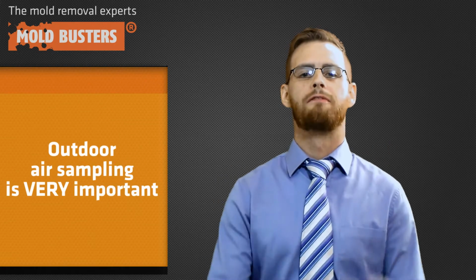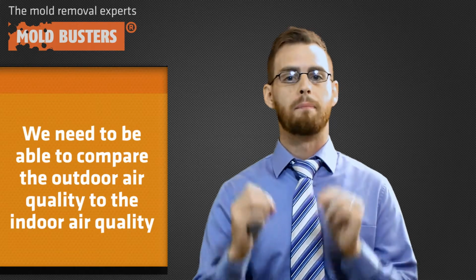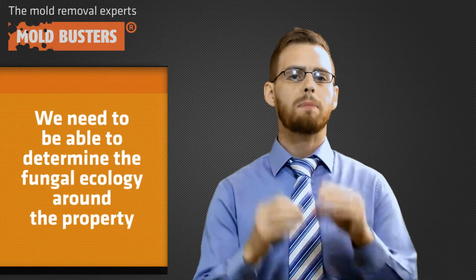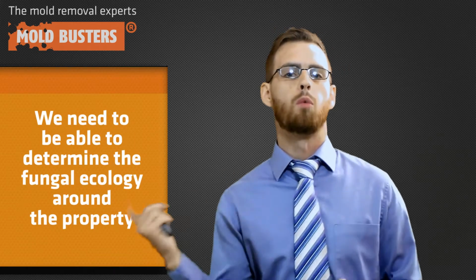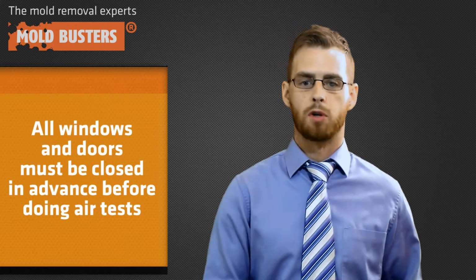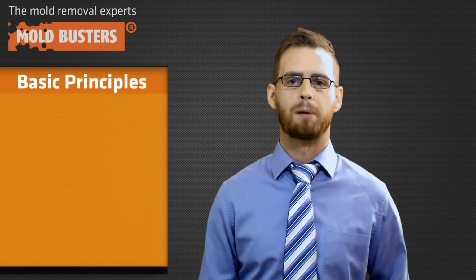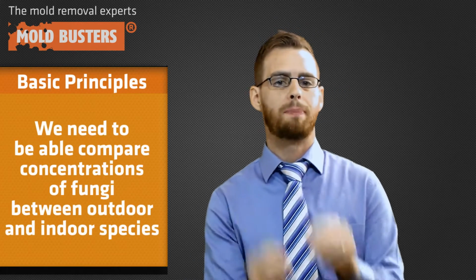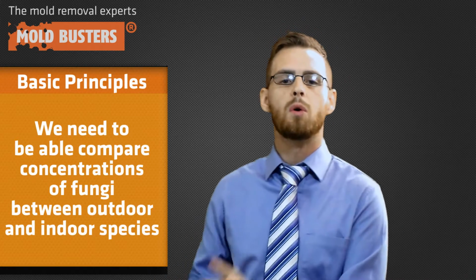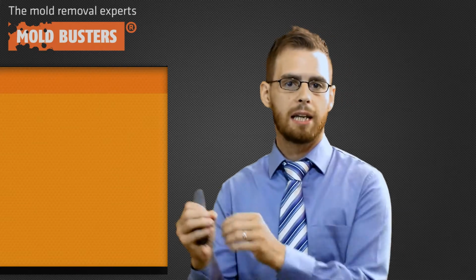Outdoor sampling is very important when doing an indoor air quality test. For example, we need to be able to compare the outdoor air quality to the indoor air quality. We need to be able to determine the fungal ecology around a given property. All windows and doors must be closed in advance before doing testing, and samples should not be taken during extreme weather. Basic principles: we need to be able to compare species and concentrations of fungi, for example mold spores, between indoor and outdoor species. We expect to find similar species indoors.